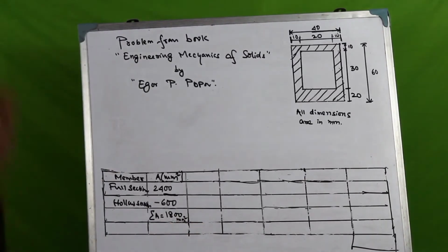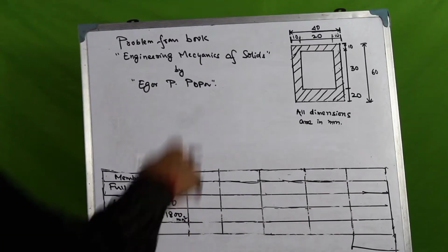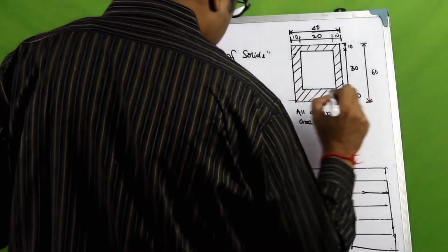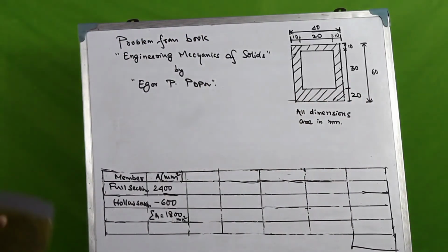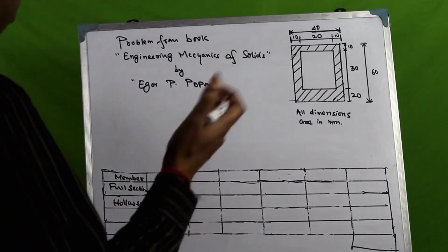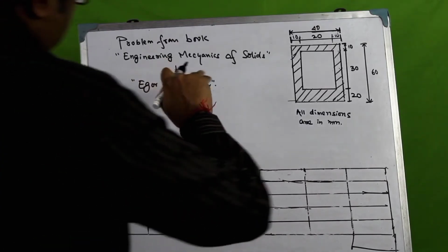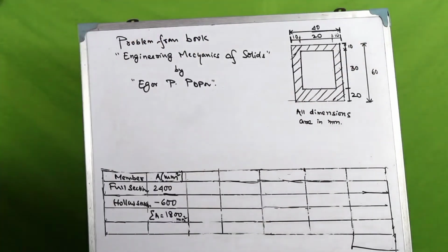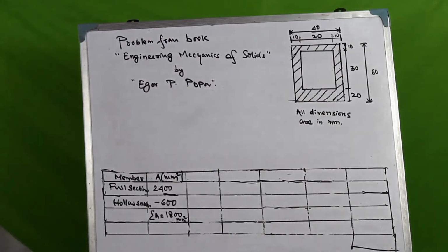The next thing that we want to find out about these 2 areas is the distance from the lowest part of the bottom flange. Remember that the intention is to find the moment of inertia about the horizontal centroidal axis, so we are trying to find the location of the centroid in the first place.